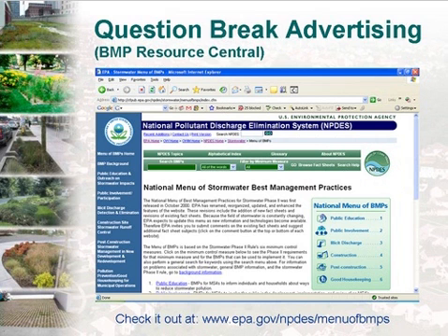Great. Another question comes from Matt in Pennsylvania. We mentioned performance of BMPs, but he points out, isn't performance essentially regional based? There's obviously freezing, and arid areas, and maybe Neely or John could comment on how regionality plays into the performance of BMPs. Yeah, absolutely. And Matt probably reflects our list of factors when we were going through what factors can affect the variability of BMP performance. And those that we listed were very site-specific. However, regional characteristics in terms of development patterns, rain patterns, extended dry periods, short rainy seasons, and when those rainy seasons occur, all have a factor in controlling BMP performance. But once again, those are factors we can't control for. So how can we accommodate our BMP designs and learn from those regional factors to improve on BMP performance?